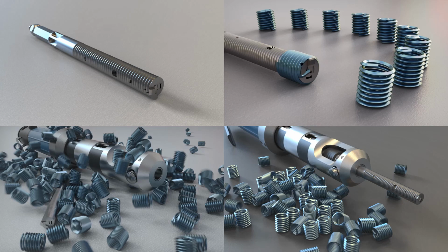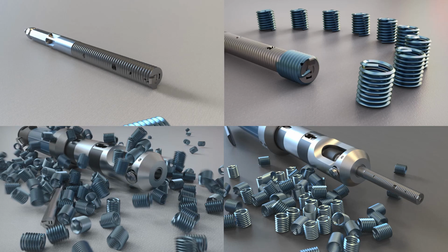And then there are other images that you can extract from KeyShot as well for marketing materials. Here you could play around with shutter speed and cameras if you wanted to put a depth of field on to draw focus into certain areas of the model. And you can also build in animations.